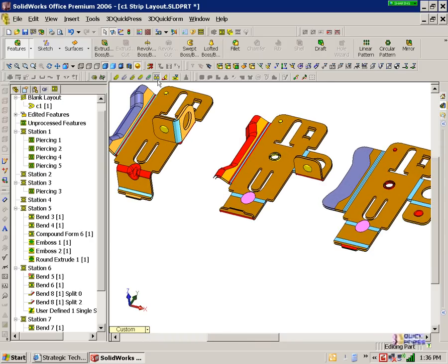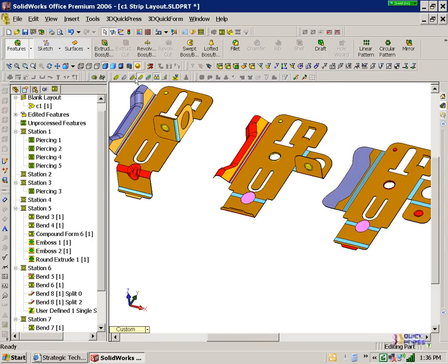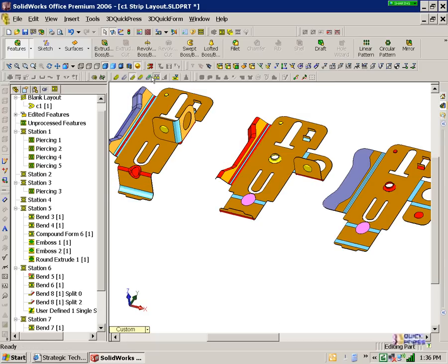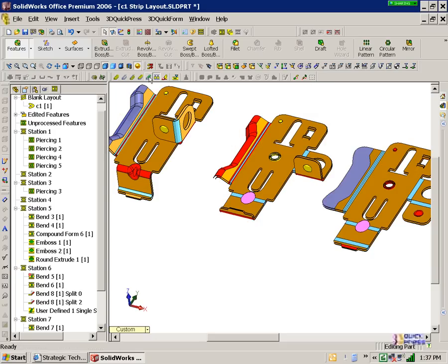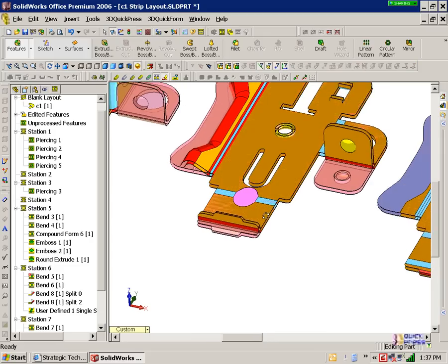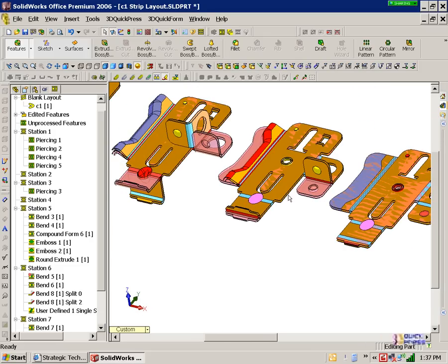I've already kind of showed you. You can turn on and off the stock, you can show the lower material, you can show the upper material. You don't have to look at it as one clunk of material. It's an intelligent strip. The other thing you can do is let's turn off the stock and let's put on superimpose here. Superimpose will allow me to go in and turn that off for a second. Oops, pilot error. Superimpose. There we go. So we can see the before and after of what's happening in that station. And yes, no matter what you rearrange, it will update.